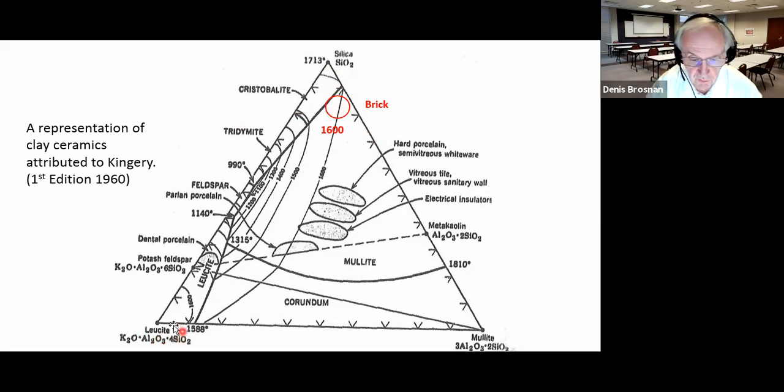We're plotting this showing potassium as an ingredient because in most heavy clay ceramics, potassium is the most active alkali phase in creating melting within the ceramic. Not the only one. Sodium certainly has a part to play, but nevertheless, we've represented it like this. You'll see this diagram again next week or next class when we talk about porcelain products.